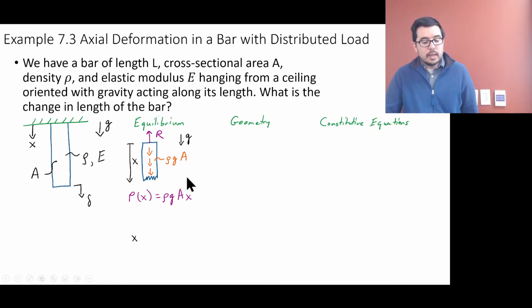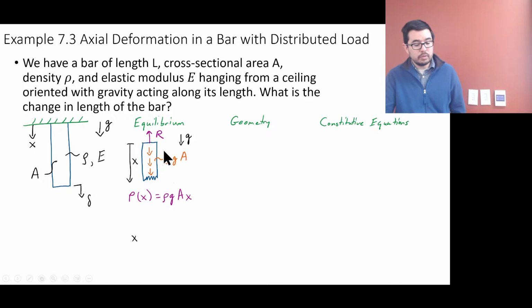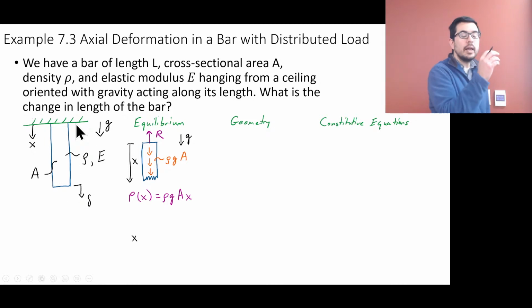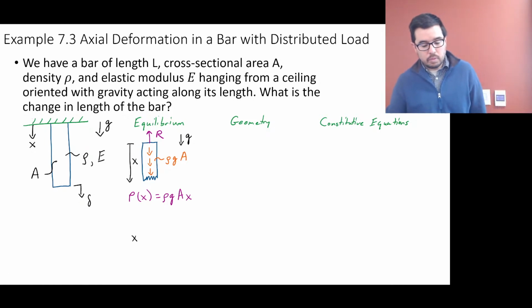If you're just a little bit down from the ceiling, you might have quite a bit of force because you have the mass of essentially the entire rest of the object acting down. If I just took this object, rho g L A, that's rho g times the volume. That's the entire reaction force that we have here.